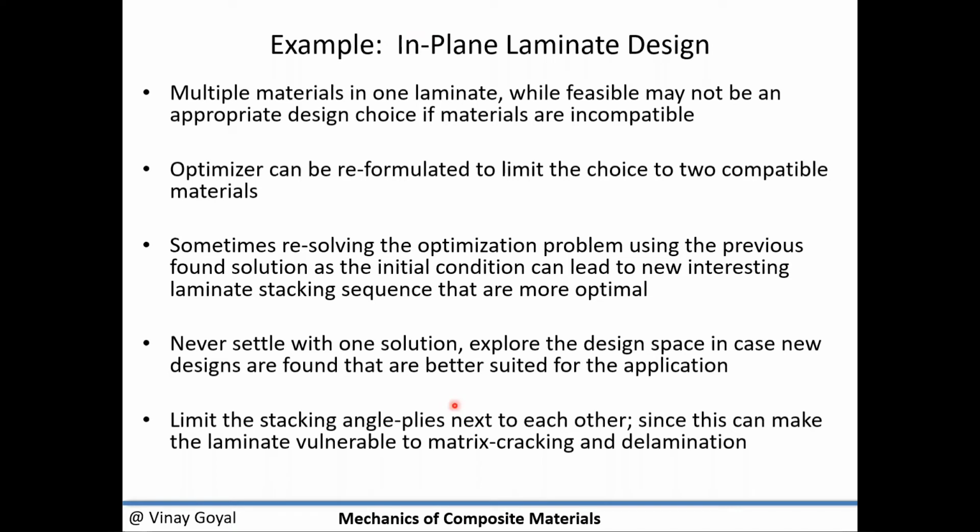You should limit the stacking sequence. You don't want a lot of angle plies next to each other. So plus minus 30, plus minus 15 next to each other may not be good, since this can lead to some matrix cracking and delaminations.